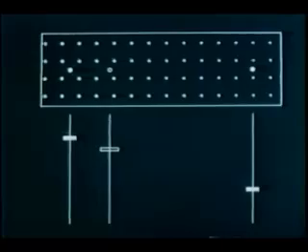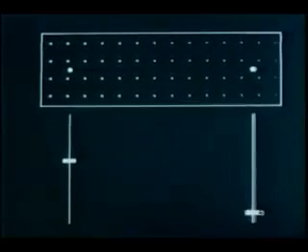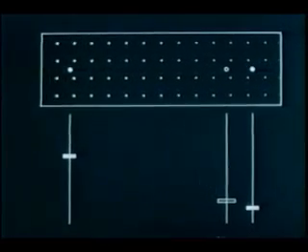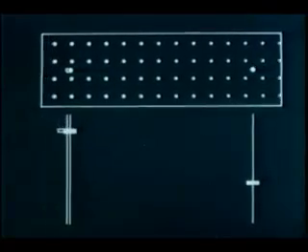The change seen at a laboratory point is not, however, since new material of originally higher intensity is being swept past. To express the change experienced by a material point in Eulerian variables, we need two terms: the change of intensity with time at a fixed point, and the intensity difference between laboratory points at a fixed time.